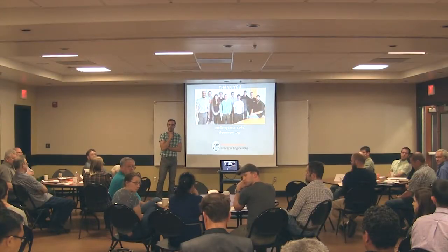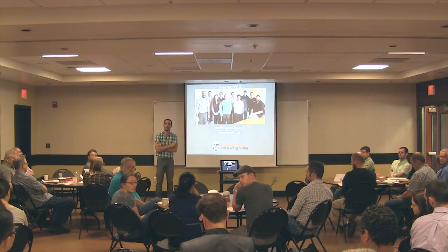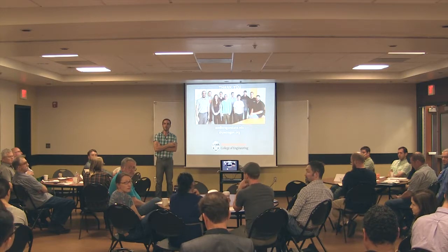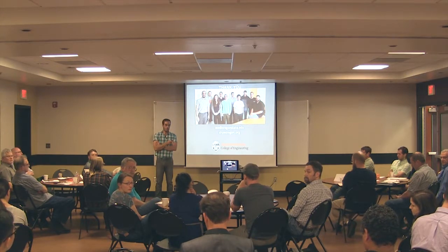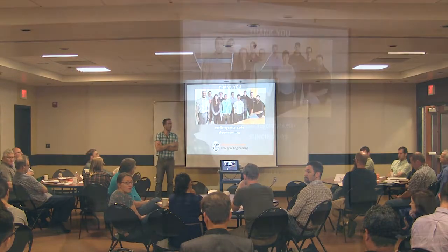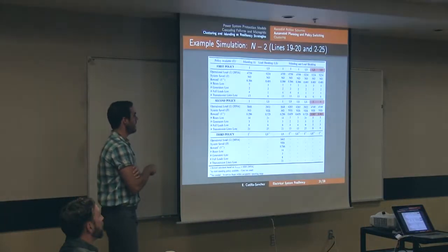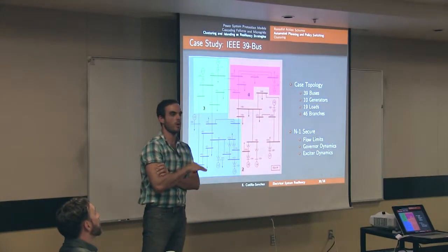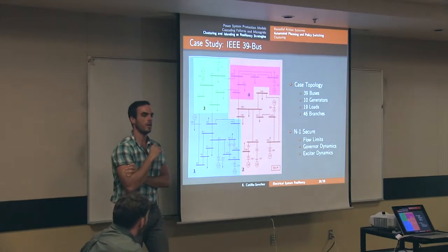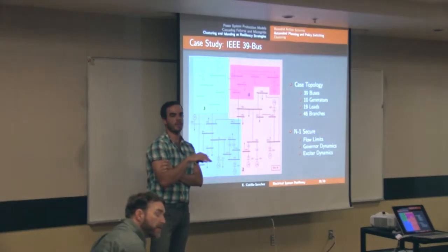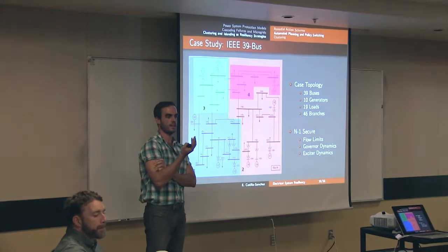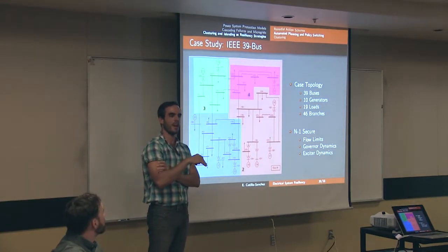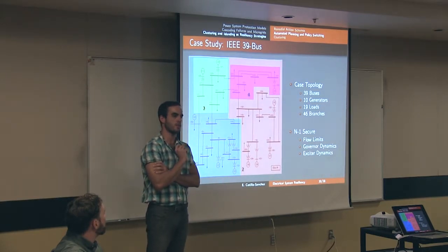Yes? I may have missed it, but in your analysis, did you prioritize different loads that you would want to keep on and want to shed, or was it more random than that and just numbers based to match the generator? In this case, on the RTS 96 case, we just did homogeneous load shedding. So we didn't add more options. Yeah, we did typical thresholds. If you look at the standards, they will say first thing that comes out is any hydro pump. Then next thing is this at this frequency. So we just used normal 5% thresholds and went with everything homogeneous.